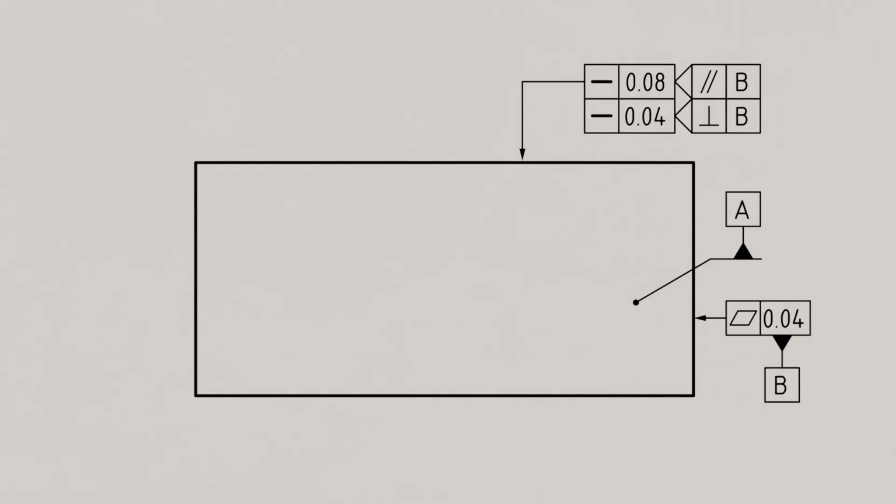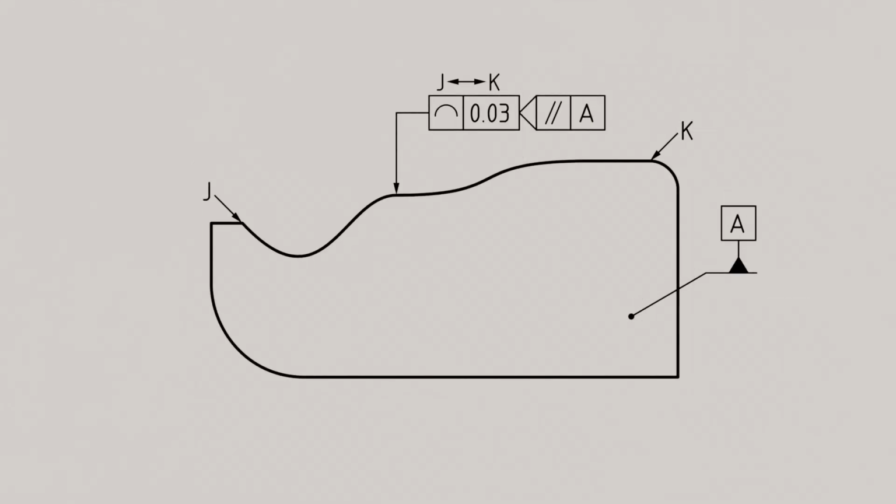The section plane indicator is not only used for straight geometry elements, but also for arbitrarily shaped geometries, such as line profiles. It is always required when a tolerance line is located on a surface, or when it is not clearly identifiable whether a line or a surface is being toleranced. However, the section plane indicator is not used for generatrices on cylindrical surfaces, or for roundness on spherical, conical, or cylindrical parts. Another auxiliary indicator is the so-called direction element indicator.